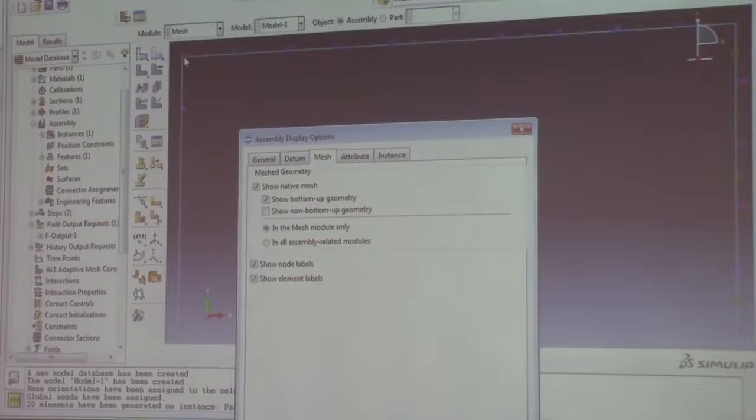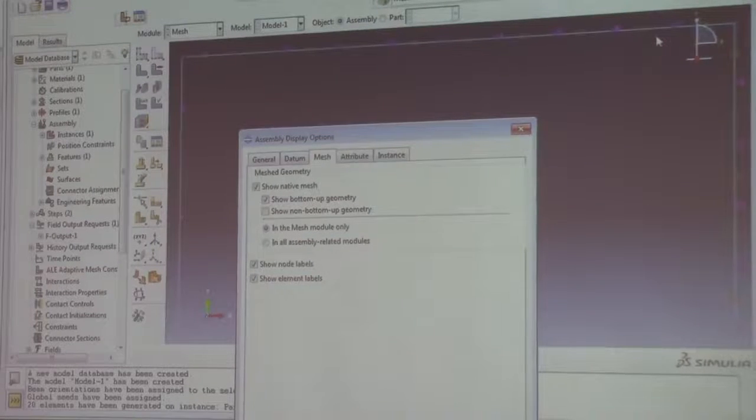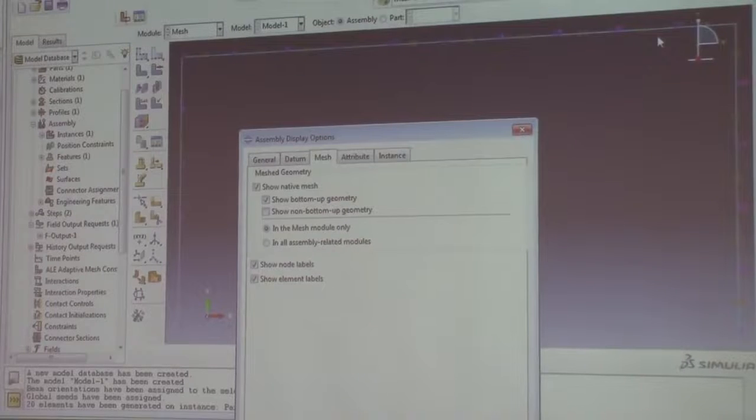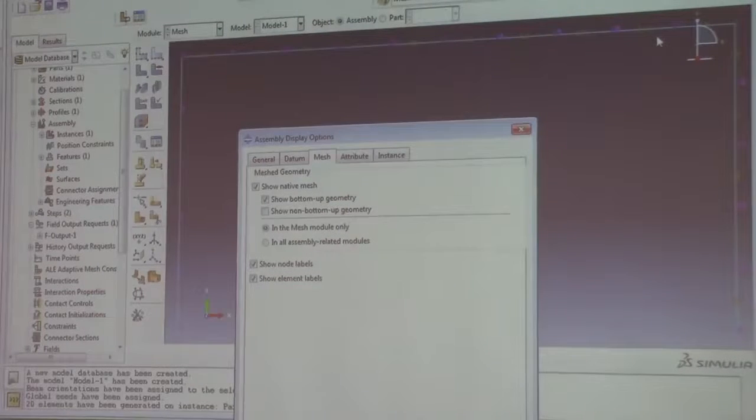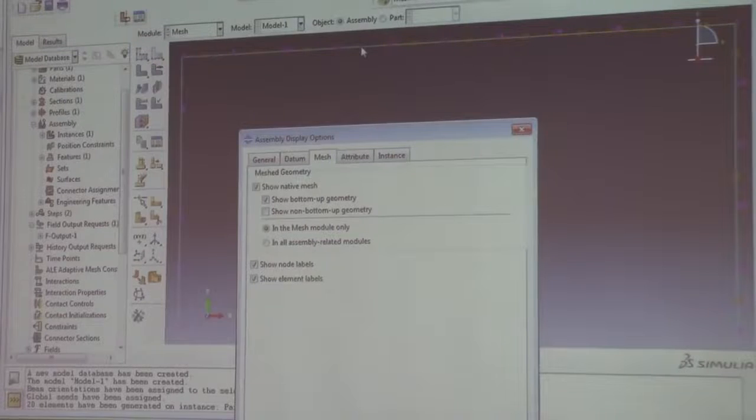Later we'll have the result of the bending moment along this beam, and Abaqus will plot this bending moment along this node label. So it's from 2, and then you see here 9, 10, 11, so from 9 to 17. And the last node is 3. Because later when we plot this bending moment along this line, we need to give the information of this node label.